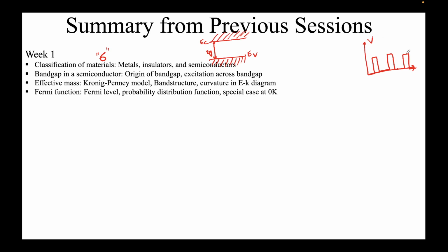And this is the potential with respect to position. What we can also now draw is something called the band structure. This is the band diagram. The band diagram is between energy and real space, so the x-axis here is space, position rather. And if we draw the energy versus wave vector k, which is 2 pi by lambda, we can now visualize these bands as something like this.